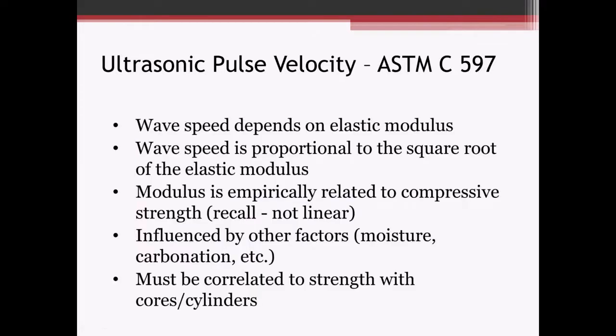timing is accurate. Again, the wave speed depends on the elastic modulus. It's proportional to the square root of the modulus. Modulus is empirically related to compressive strength. It's not linear. Again, it's influenced by some other factors: moisture, carbonation. If you've got a surface that's heavily carbonated, the carbonation actually densifies the surface of the concrete and will increase your wave velocity.